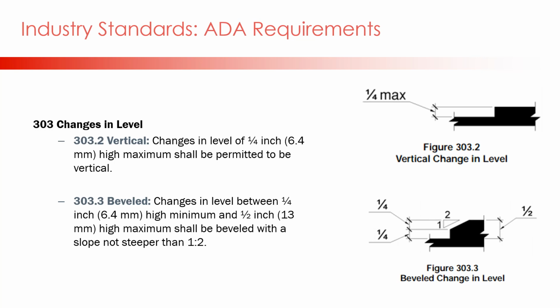Many entrance floor mats are available with a 1/2 inch or less profile. These products may be surface mounted with a beveled frame and comply with the ADA. There are some options for a 1/4 inch mat, but there is minimal capacity to retain dirt within a 1/4 inch system. Given the variety of choices of products with a 1/2 inch profile, it is highly recommended to avoid the 1/4 inch systems. A system that has a profile greater than 1/2 inch must be recessed.